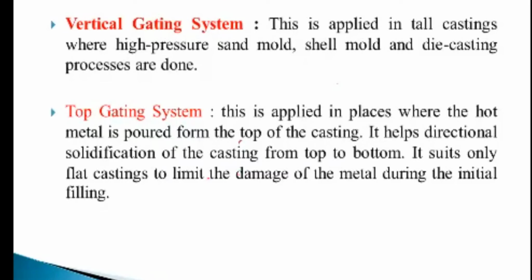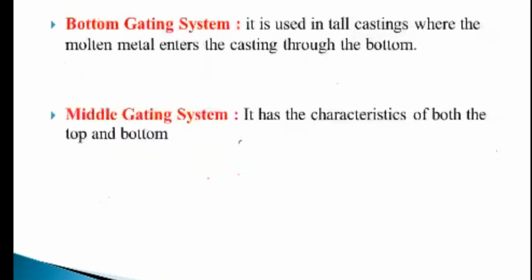If the metal comes directly from the top, its velocity may be high and it may damage the mold cavity during initial filling. So we have to control the velocity and ensure that the mold cavity is not damaged. Then next comes your bottom gating system.